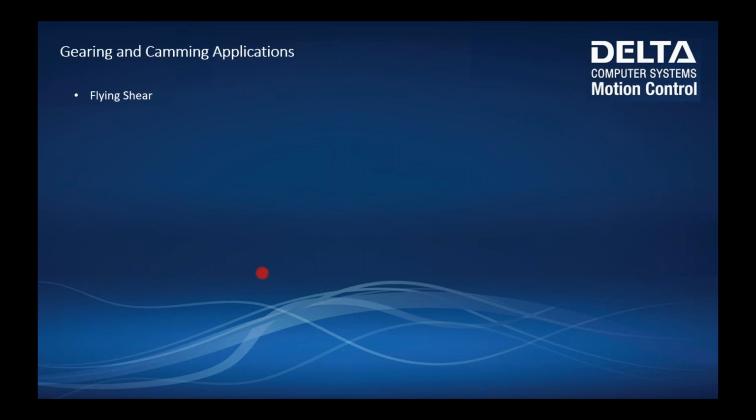Okay, so here's a list of a few applications. The flying shear, we talked about that one here in the beginning. Animation can be a great one. This is more camming, I would say. You can cam an entire animation sequence to a curve and run everything. You can change the phase that different axes are in. If anyone has seen our 12-axis display demo, it's a great example of what something like that would look like. You've got one axis following the other, and they're all a little bit out of phase from each other, so it ends up looking like a sine wave.